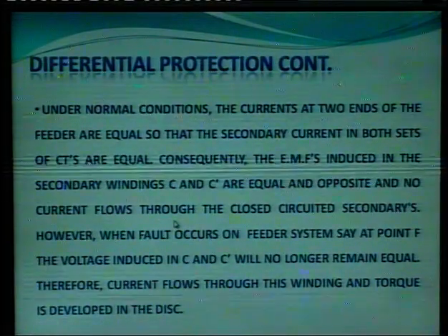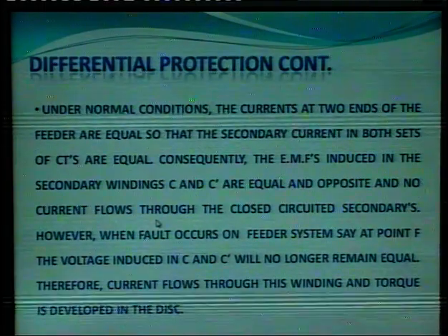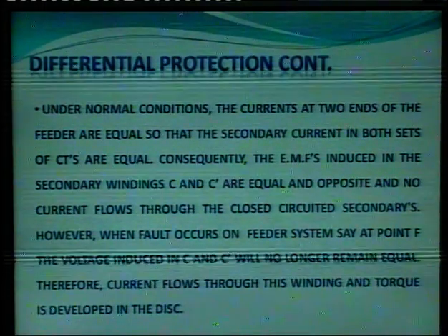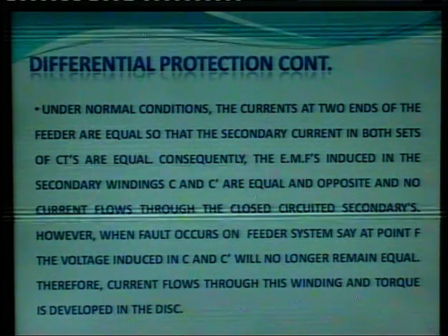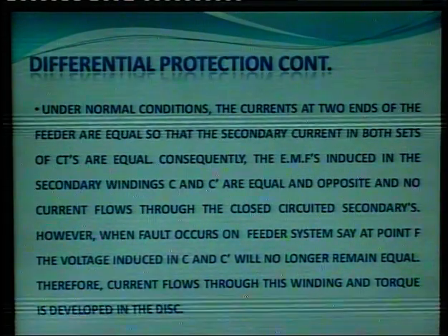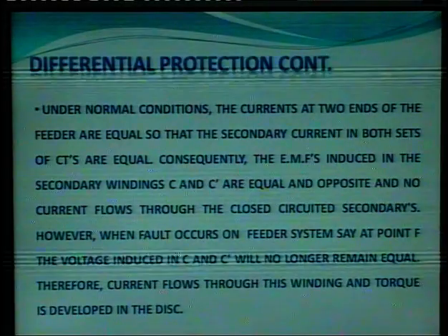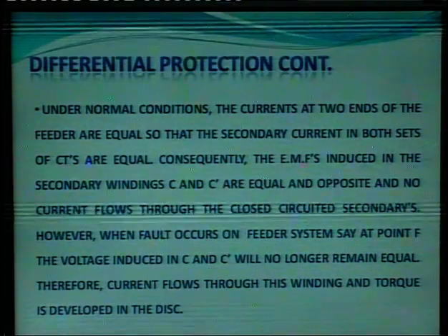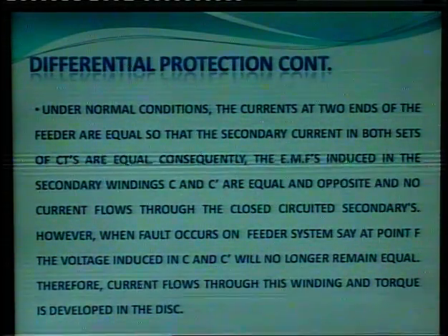Now, under the normal conditions, the currents at the two ends of the feeder are equal, so the secondary currents in both sets of CTs are equal.